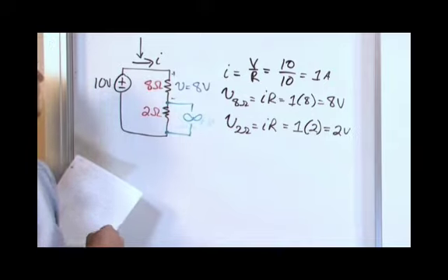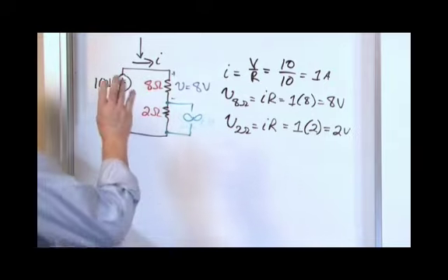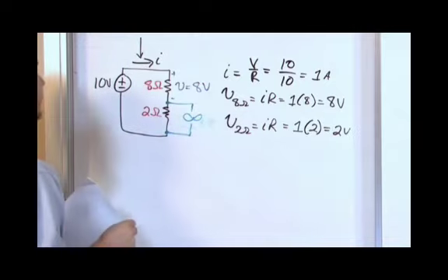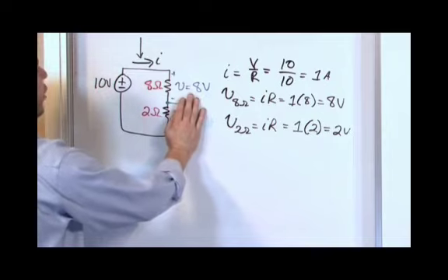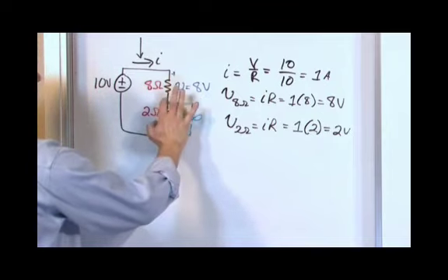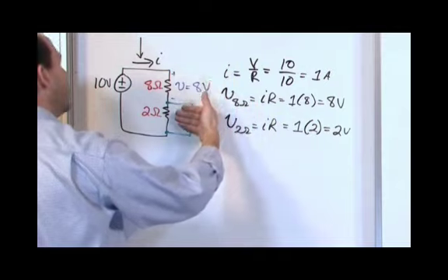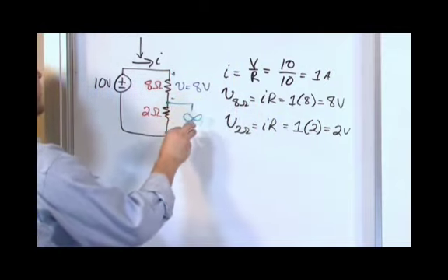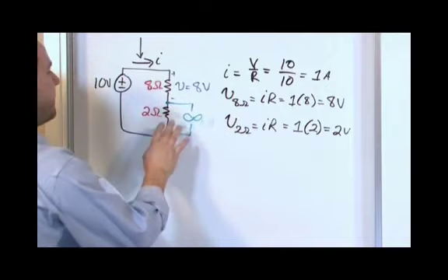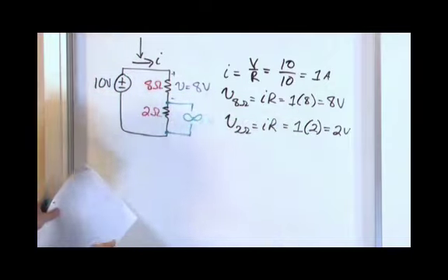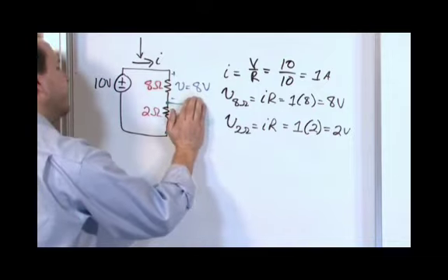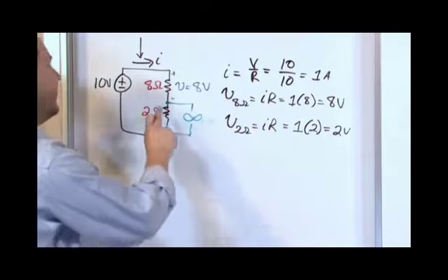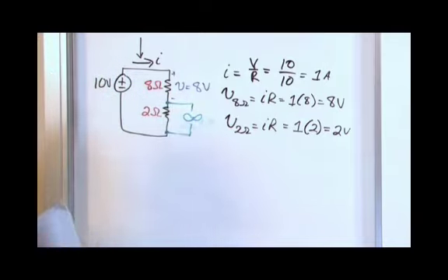All right, so to recap before we do a problem, here's a voltage divider. I'm going to show you how to calculate easily how the voltages are divided in a second here. If you don't have any load connected at all, it's called the no load voltage on my output terminals. Once I connect something to it, it's called the loaded down voltage. And depending on the resistance of whatever it is I hook up, I may change things a little bit and maybe I won't get exactly 2 volts out. It depends on the resistance. The higher the resistor value of whatever it is I connect here, the more pure my original voltage divider is, and the exact amount of voltage drop that I calculate is what I'm going to actually get.